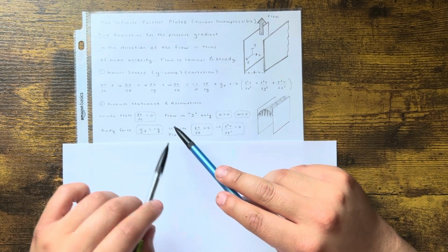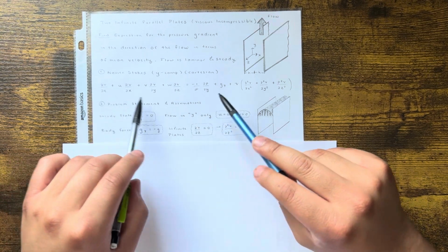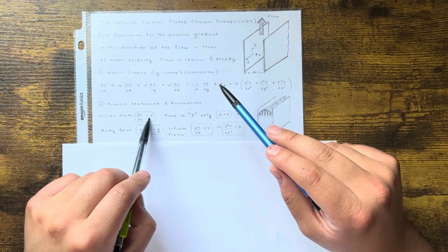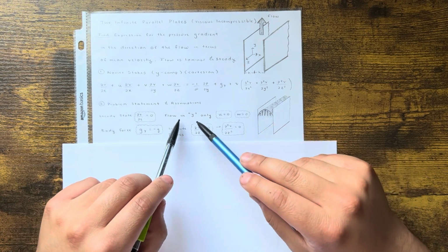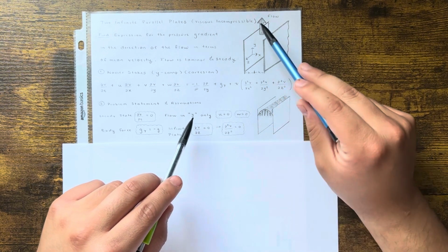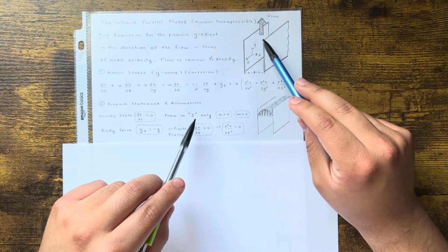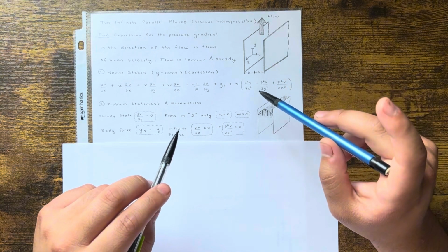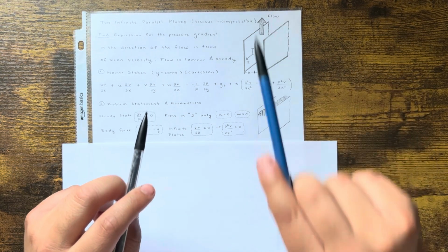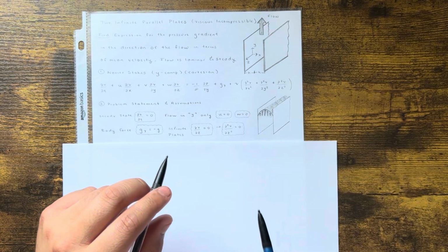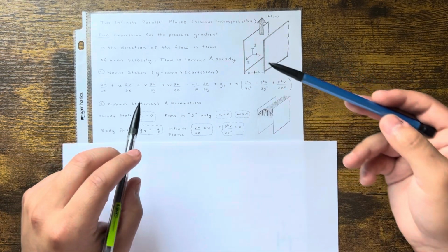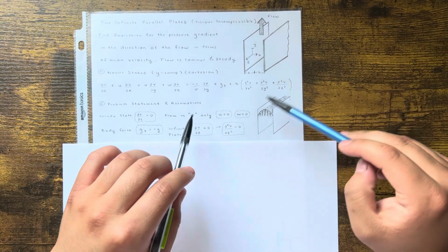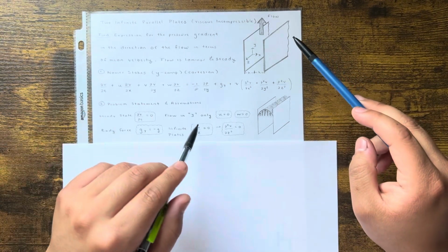So steady state, right? The t term, anything with a t, is 0 because it doesn't change with respect to time. It's steady. So that term went away, okay? The flow is only in the y direction only. It goes up in this case, right? So since we're going up, gravity is bringing it down, just something to keep in mind. So that means there's something pushing, fighting against gravity, kind of pushing it up like a pump or something. But I mean, that doesn't matter. That's just kind of like to get you guys to think a little bit. That's why the flow is going upwards in this case.